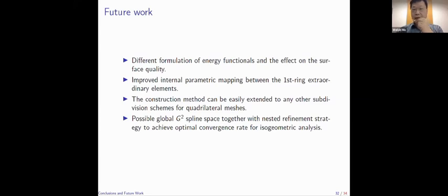We verified, for example, the convergence for other geometric analysis. I think for stability, hopefully it should be okay. In terms of the high degree, I agree that degree 7 is indeed very high compared with degree 3, which we use most of the time. However, from some other articles, we see that in order to achieve local G2 continuity, the minimum degree we can use is bi-6.